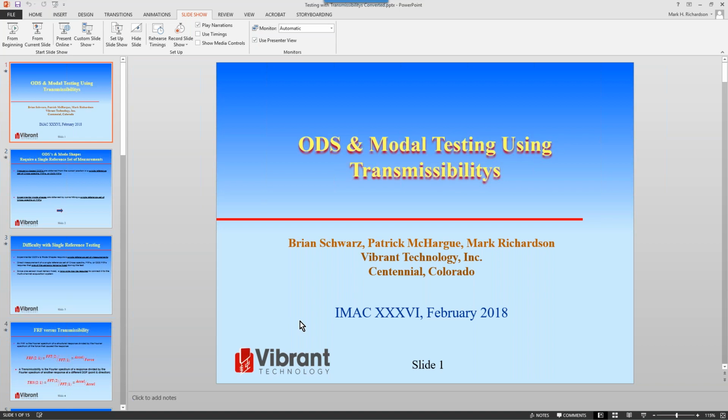So you can see here the opening. This is a technical paper that we are preparing for the IMAC. That's the International Modal Analysis Conference. It's coming up in February next year, and the title is ODS and Modal Testing Using Transmissibilities. Now, normally we don't use transmissibilities. We use frequency response functions, or we use ODS FRFs, or we use cross-spectrum measurements. So we're going to talk about all these different types of measurements today and what's different about them.